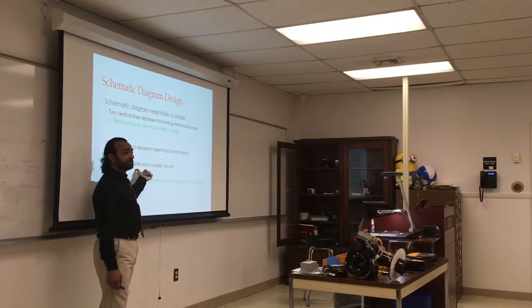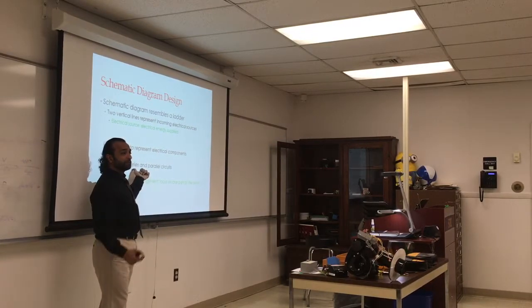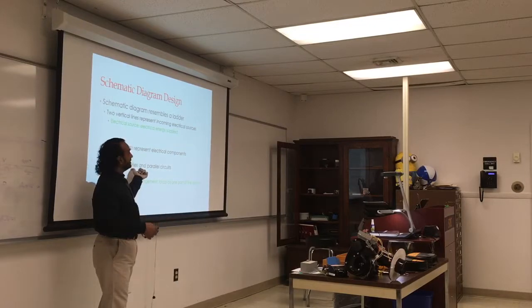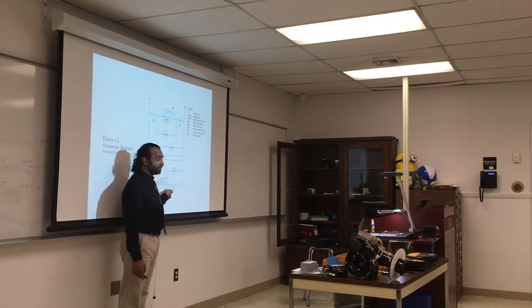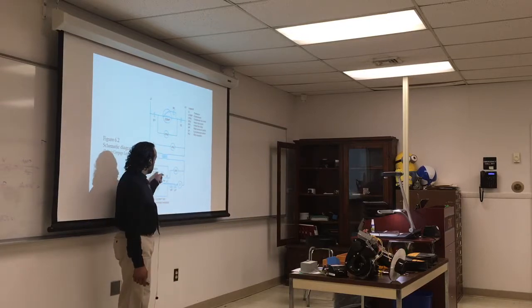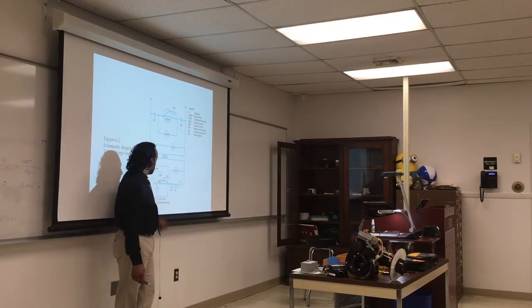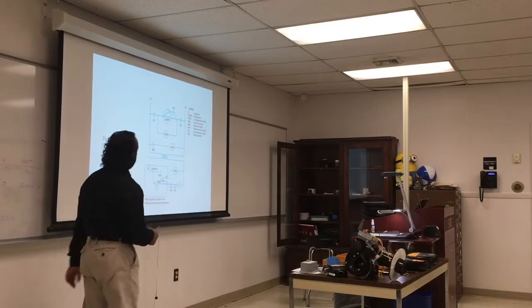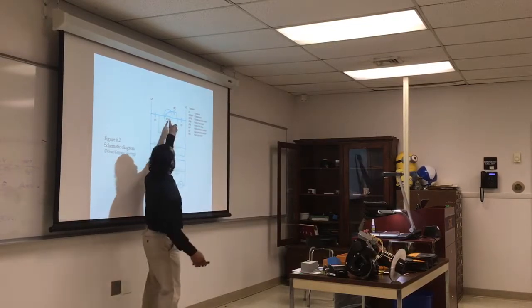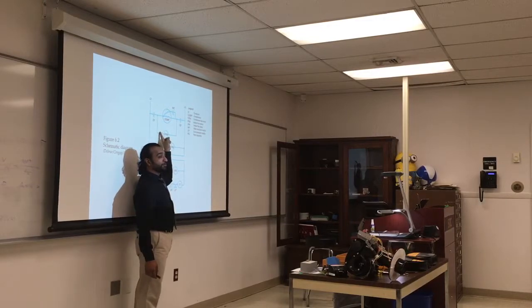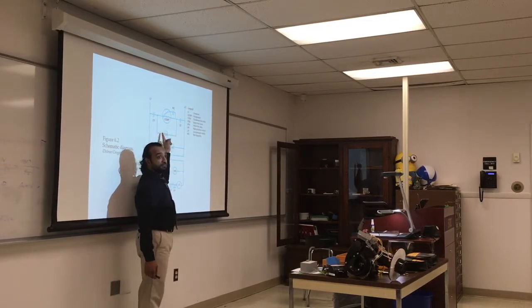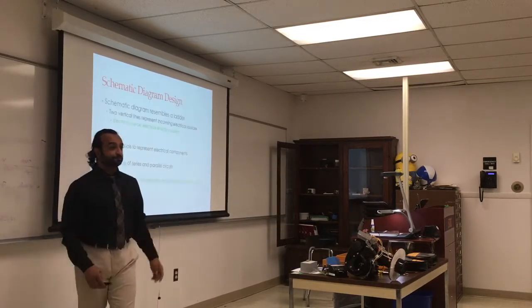What is connected in series? Switches. Switches for safety and control. Look at these switches that are connected in series, right? And this control circuit is connected in series as well. In parallel are the components. Look at these components. These are loads, right? They are connected in parallel, so each of them will get how many volts? Same one, 110 or 240.